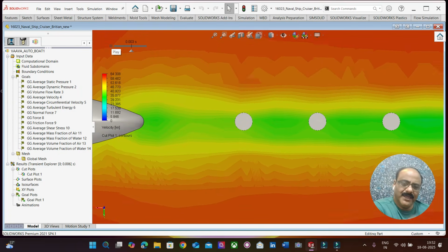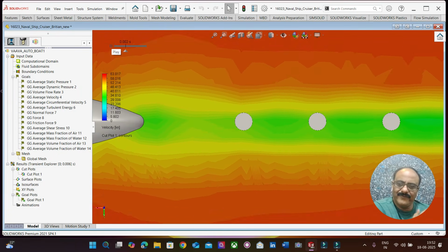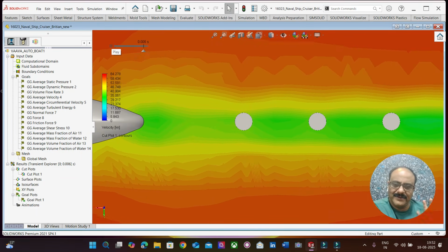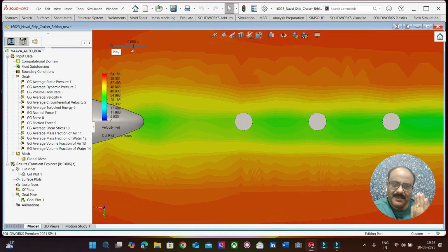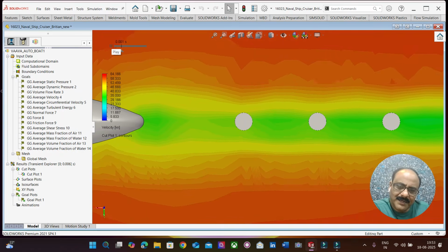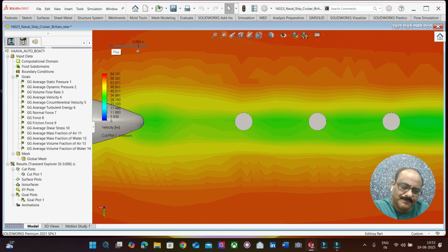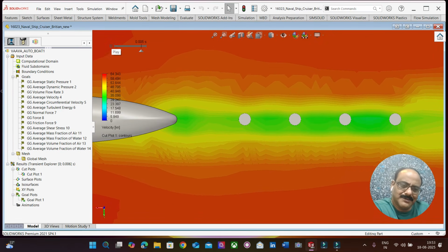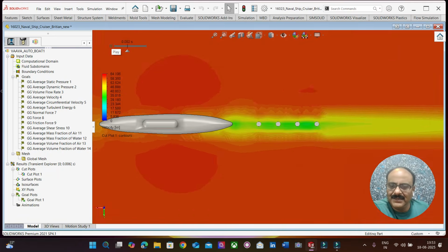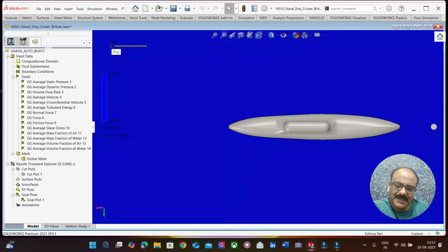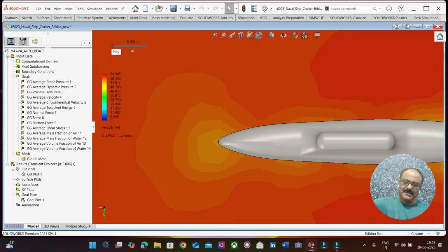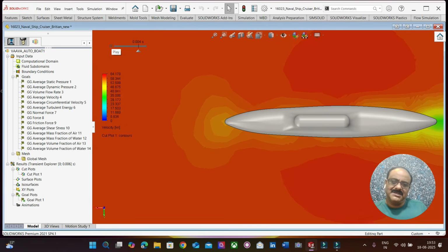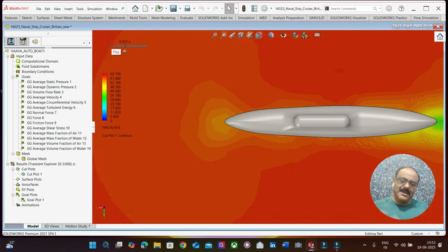Now, if we refine the mesh, the cells, whatever I showed you, the basic mesh or the advanced channel refined mesh, we will find that these vortexes are well formed. Here we already have the vortex between the circular bodies or the bluff bodies. From this we can understand that there is a huge circular region with bigger waves, and there is a possibility of breaking these waves also.